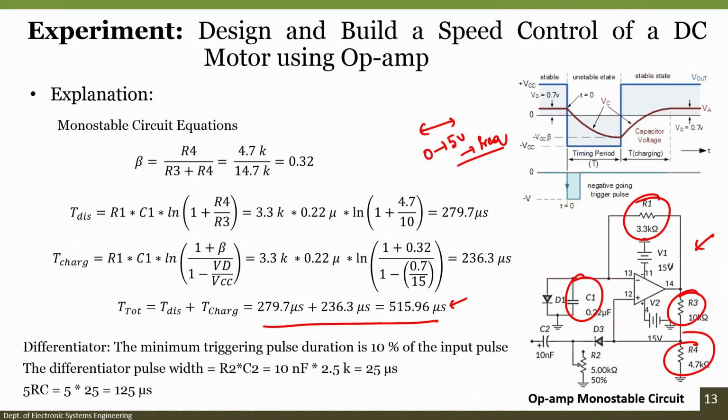The operating voltage is 5 volts maximum in this particular case study. For 5 volts, we observed the on time as well as the off time, and by adding both we get the total time. This total time is higher than the total time we got from the discharging and charging of the capacitor. As a result, this will work completely for that particular range of input voltage, that is, for this particular frequency signal.